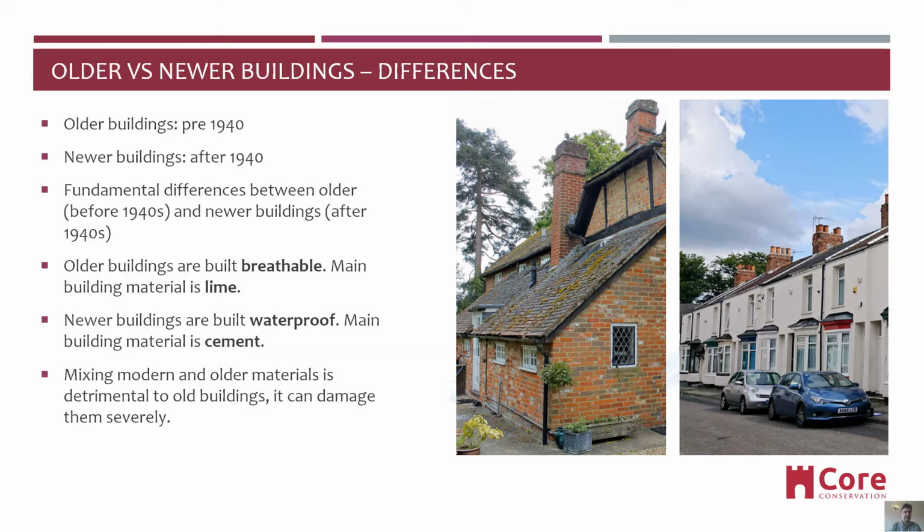Older buildings are built breathable, the main building material being lime. Newer buildings, on the other hand, are built waterproof, the building material being cement. Mixing modern and older building materials is detrimental to all buildings because it can damage them severely.